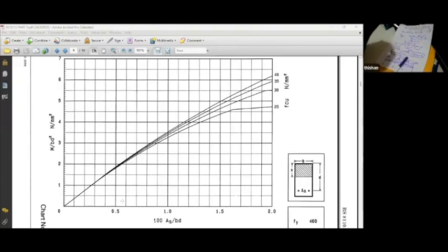What is the main advantage? Shear capacity is high when the beam is wide. It is very easy to do the construction. No honeycombs. No leaks. Because it has plenty of space, we can vibrate it properly. We can pour the concrete from above because the reinforcement has sufficient gap. And the structure is also very strong because it has high shear capacity.